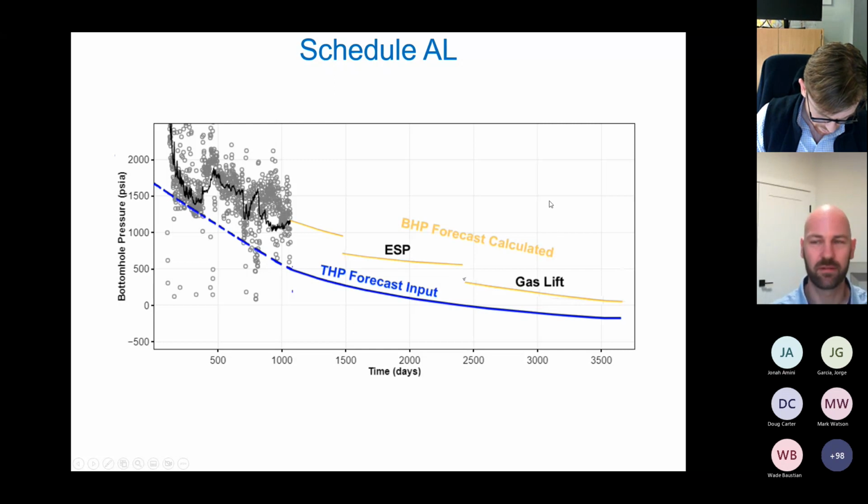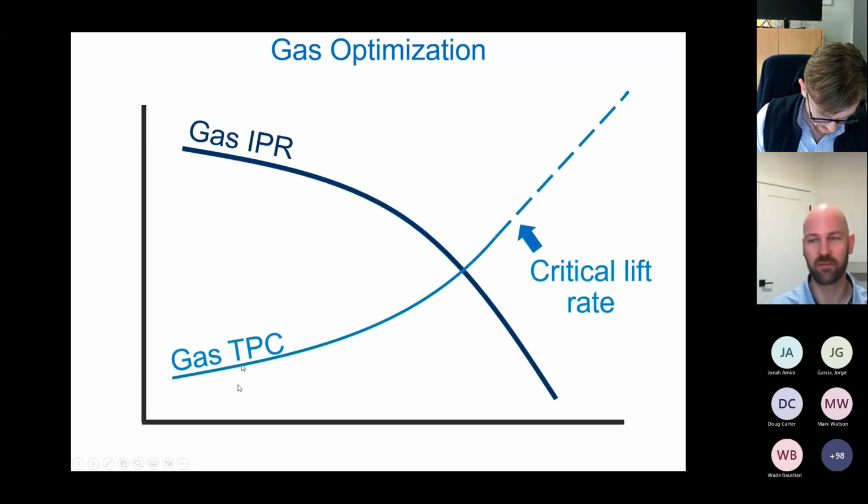So I think this is going to be really a game changer in terms of just doing long-term planning for production optimization, really based off the numerical model as the replacement to an IPR curve. The other thing, of course, is right now we do the oil IPR tubing performance curves. Next is going to be coming a gas, right? Gas inflow and outflow curve. So we'll be using the Forchheimer method for the IPR curve initially. We might do some more complicated ones later.